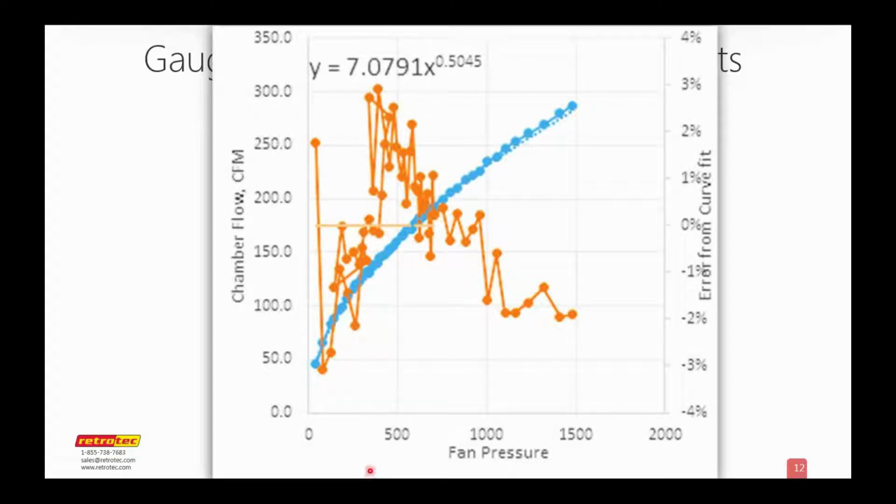So when you write something in the manual, do this and do that, then you're not going to be surprised. We do put error traps in our gauges that prevent you from taking readings that will not be accurate. So when the back pressure goes really high, you'll get a series of dots, and it won't give you a reading. So something is wrong there, and that typically happens when the fan is running very slowly at a high back pressure. The gauge will actually prevent you from getting a reading.